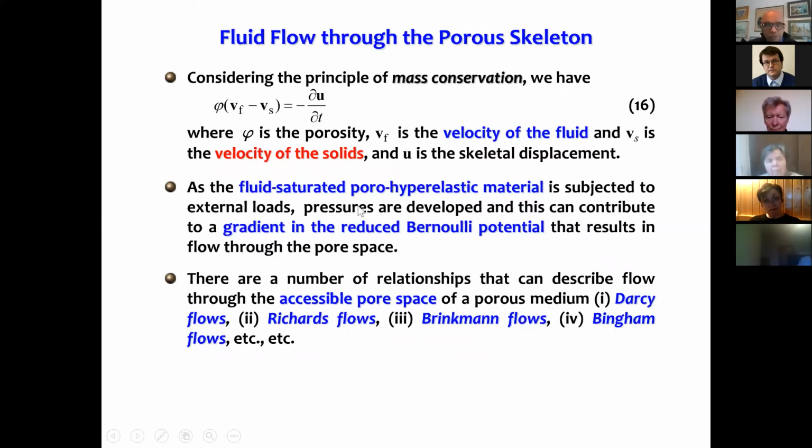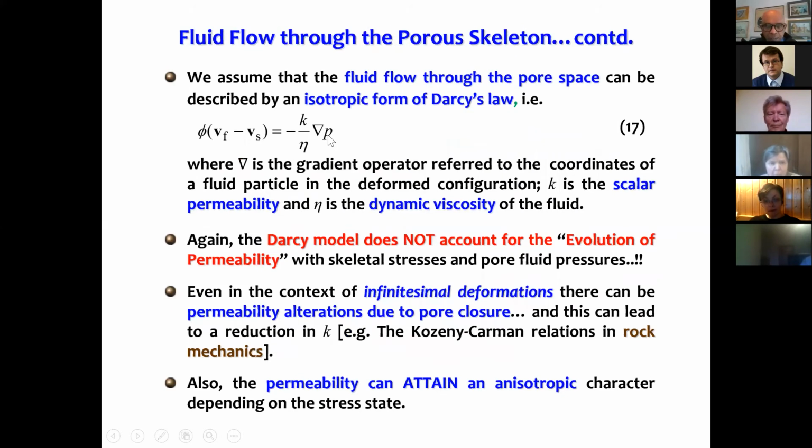So if it is Darcy flow, then the right-hand side of the, excuse me, I'll go back again. This one comes out to be exactly characteristic. And again, I reiterate that I can also make the fluid flow direction dependent by stretching it. So if you give large strains to the material, then there can be pore adjustment. So the pores will align themselves to give favorable fluid flow in one direction compared to the other. It can have plasticity effects, which are also anisotropic. So that's an entirely different discussion.